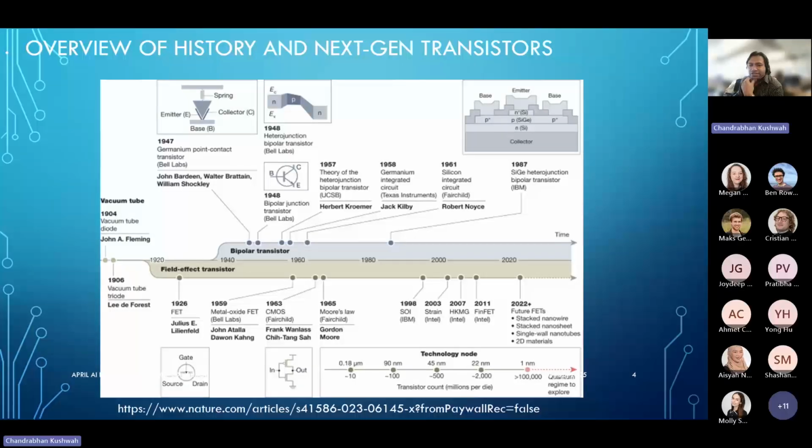It's very interesting to see that according to the latest International Roadmap for Devices and Systems, further scaling beyond the 5 nanometer threshold may plateau at a gate length of 40 nanometer for low power and 12 nanometer for high performance applications, potentially hindering future progress. So this is a very challenging task. This perspective therefore aims to spotlight the most viable sub 5 nanometer logic technology and delineate the critical research directions needed, helping to streamline and strengthen ongoing efforts across the field.